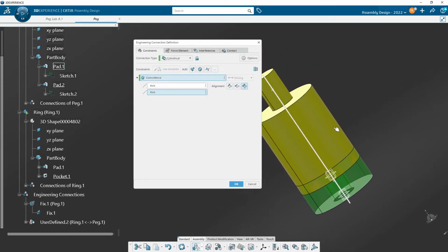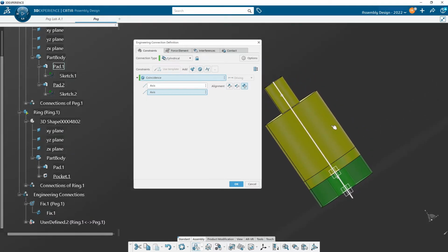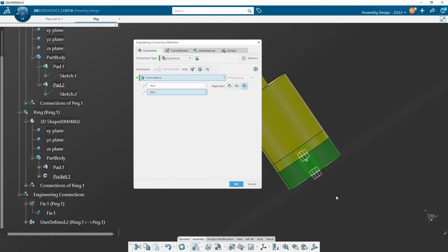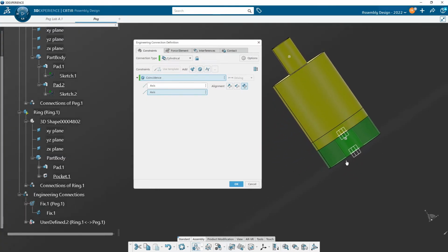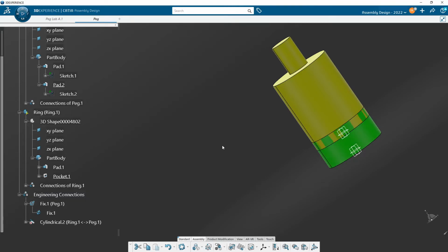But again, you might not have been expecting this. From the last lab, I talked about the same kind of thing. It puts the two centers together. In the last one, it was a contact constraint. It puts them together the quickest, shortest route. So this thing was currently over here, so it snapped it together. Should we be concerned about that? No, not a single bit, because we know we have other constraints to add. There's our interference. Yeah, we'll deal with that in a second.